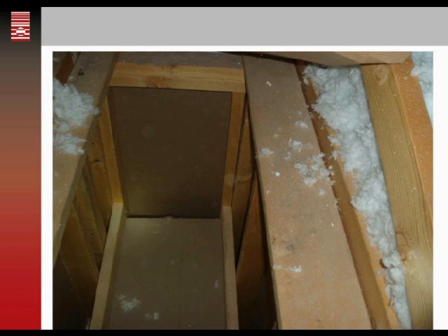As you can see here, there's a drop ceiling detail. In some of the units, they had just filled this up full of insulation and insulated over the top. In other cases, they had stapled cardboard over the top. Stapling the cardboard wasn't sealed. Helped a little bit, but you have to remember that this is a 2-story building with a basement, so a tall building with extreme cold, below zero temperatures.